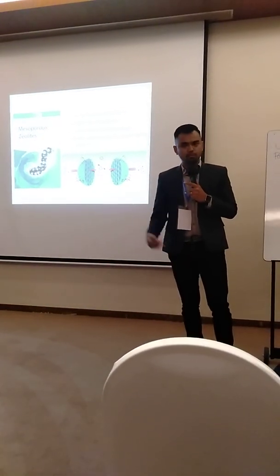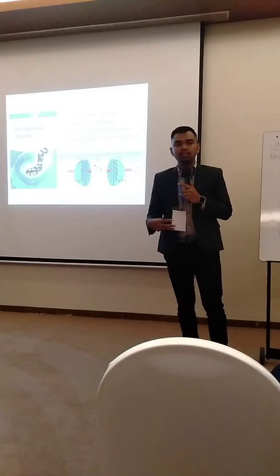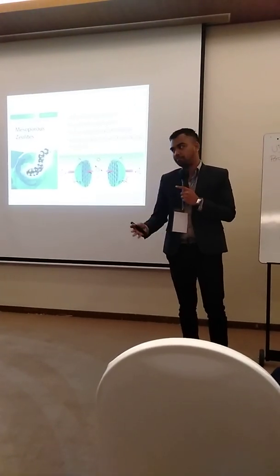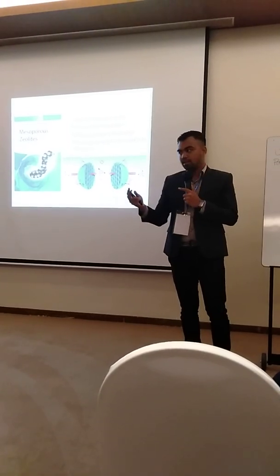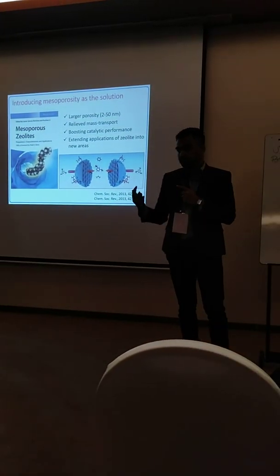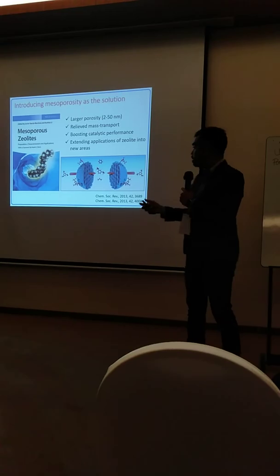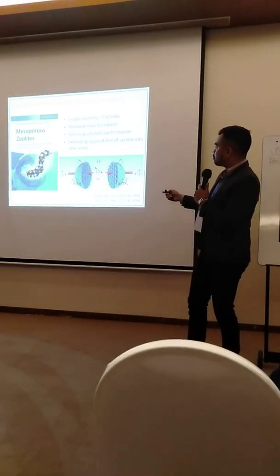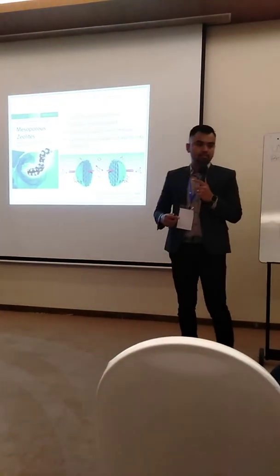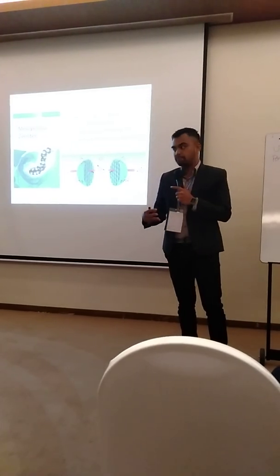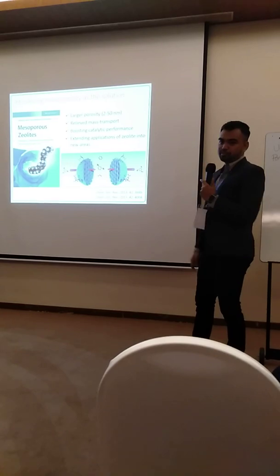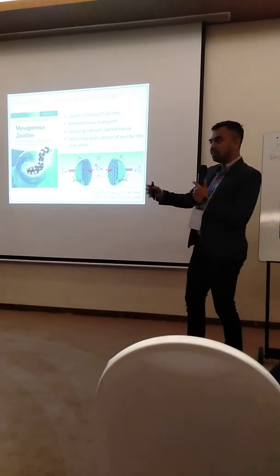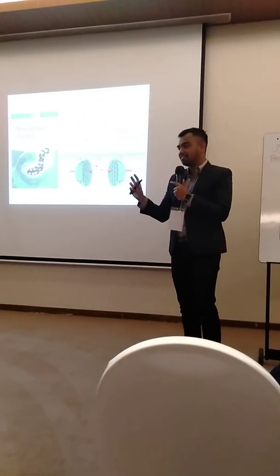So what is the solution then? One of several solutions is introducing mesoporosity. A mesopore is a larger pore, larger than micropores, from 2 to 50 nanometers. So it gives better mass transport because now the diffusion path is larger.